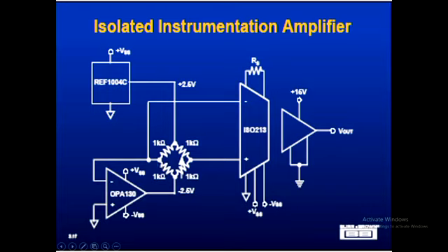So it will set up a voltage across this resistor of value 2.5 volts, okay. And 0 at this end, so this end's got to be minus 2.5 volts. Agreed? Good. So plus 2.5 this end, minus 2.5 at that end.